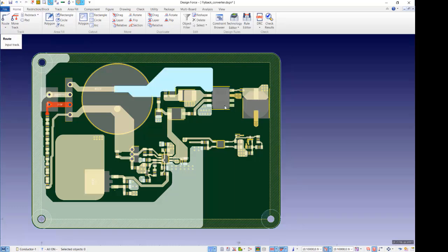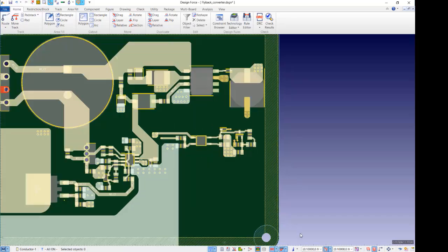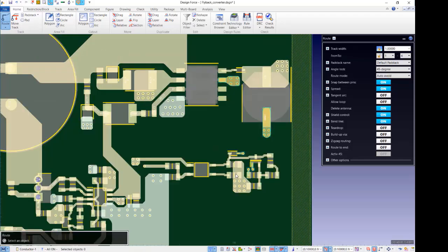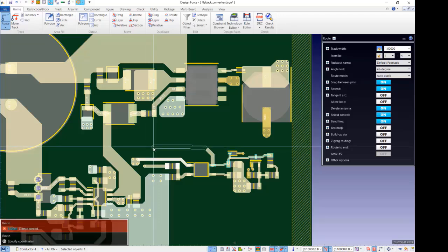Okay, so for example, if I was to input this track here across a barrier, notice that I'm trying to move my cursor here, it won't let me go because it's obeying that rule. So I can come in here, for example, and you notice how it will cut through copper, because obviously it's dynamic, but any tracks, it's showing that it's automatically trying to keep that 4mm space.